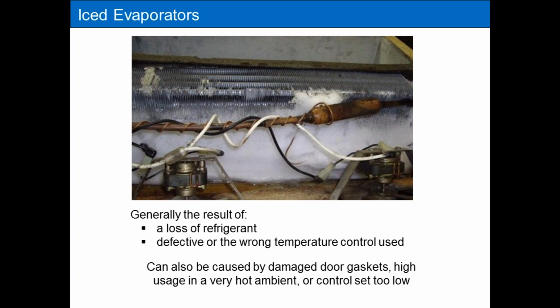It could also be caused by high usage in a high ambient, where the unit runs and never shuts off because they're opening the door, or the gasket, the door never closes properly, so it never seals the compartment so it can drop temperature. So a damaged door gasket, high usage in a high ambient, or particularly the temperature control that's just set too low. So those are some things that can cause you to have an iced evaporator, and we're going to talk about how you can define which is which.